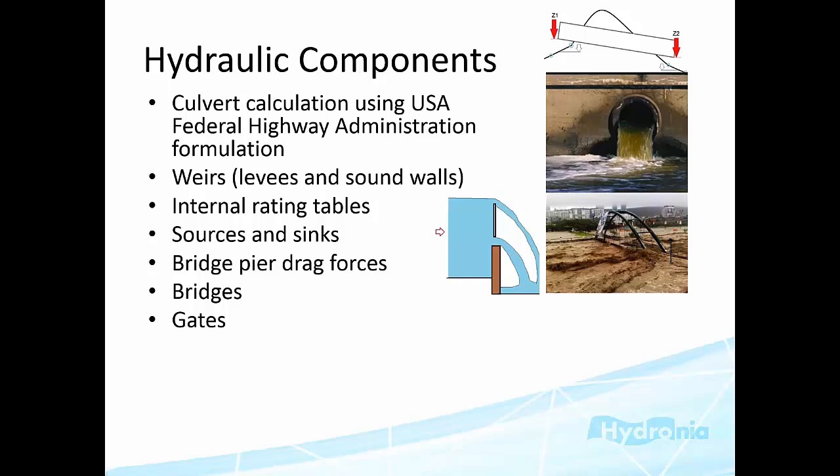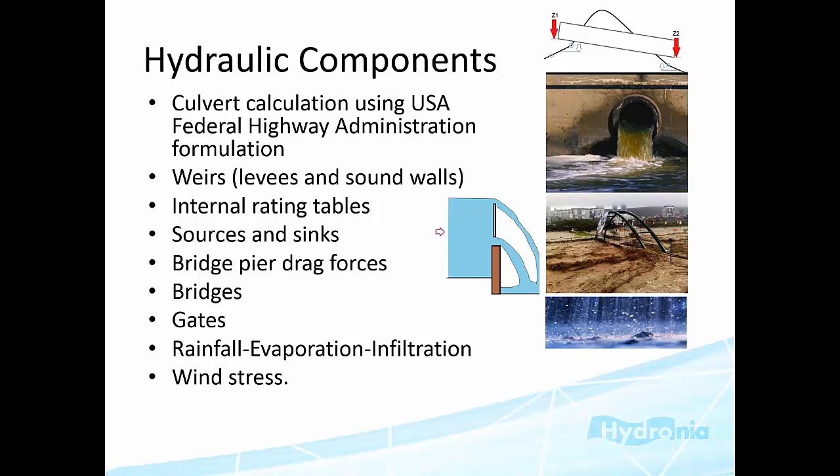The model also handles gates, and you can operate the gate with a time variable operation law. And as I said, it also does hydrologic analysis of rainfall, evaporation, and infiltration. We recently added the wind component, so especially in wide area estuaries, you can also model wind stress on the surface that may drive the flow in some situations.